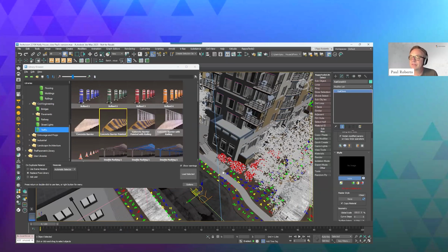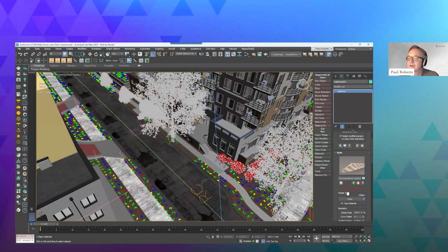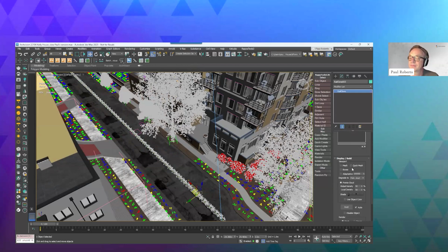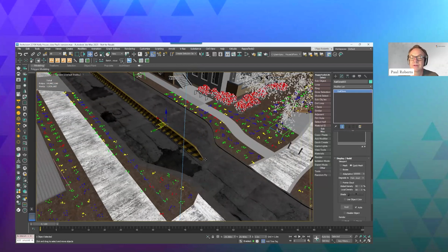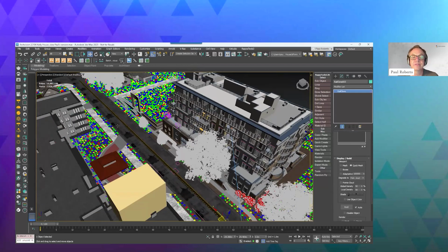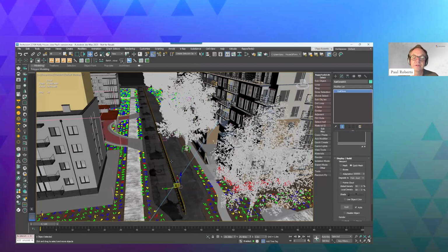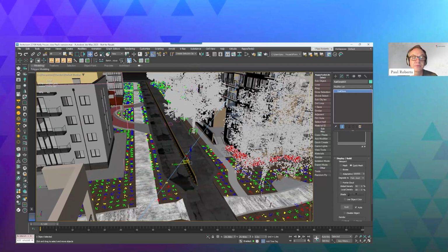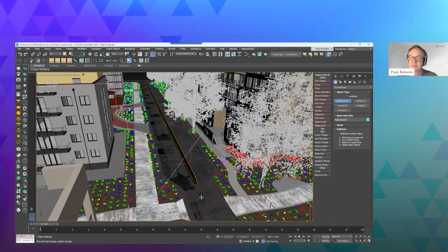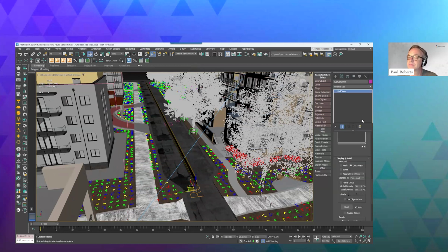Just accept whatever the messages are. And then once again, it's a simple case of coming down to base objects and clicking to add it in the scene. We've got my geometry going down there. You can see it fits the spline. I could also add some streetlights, for example, so I might do the same thing again.